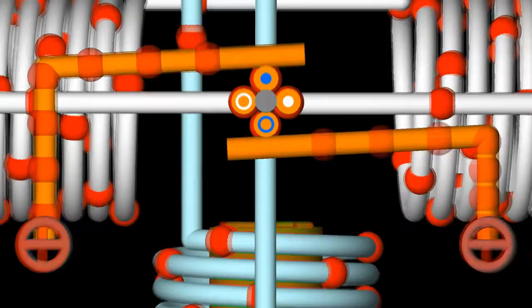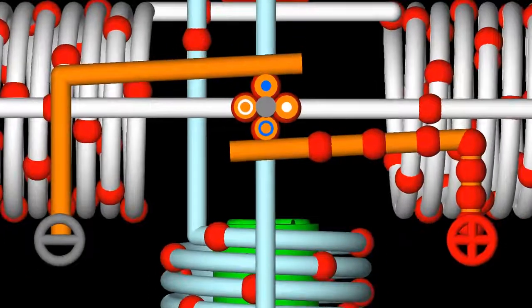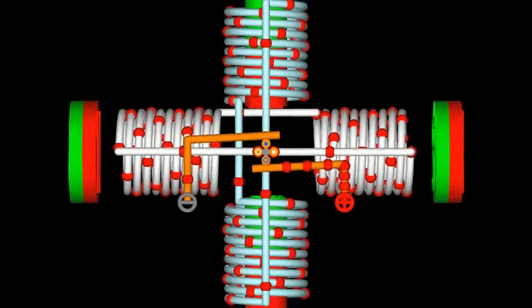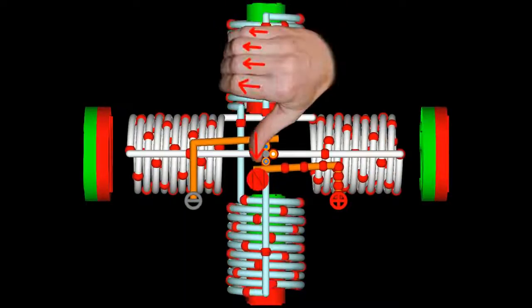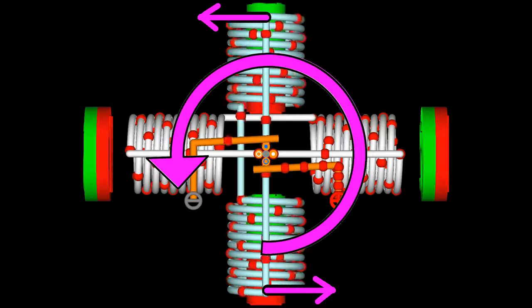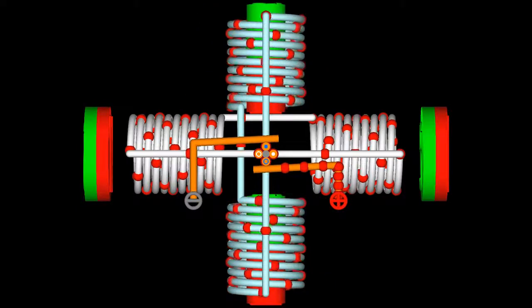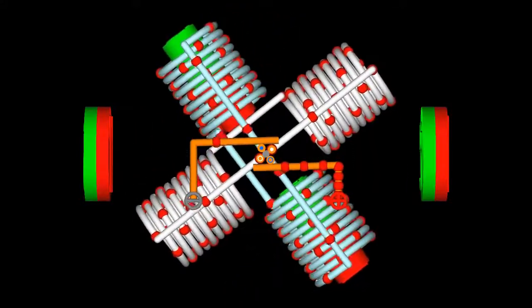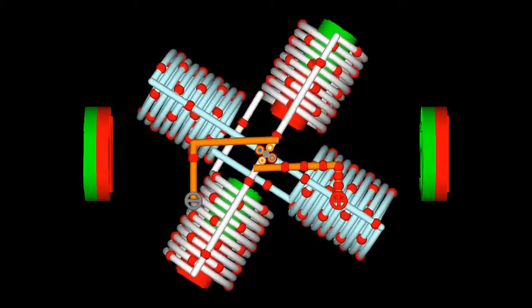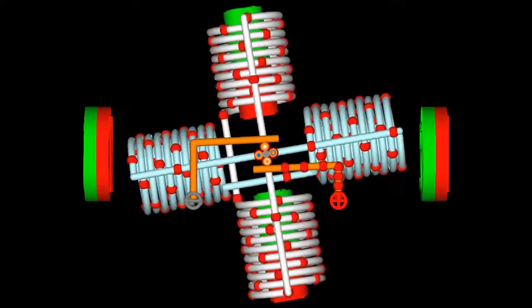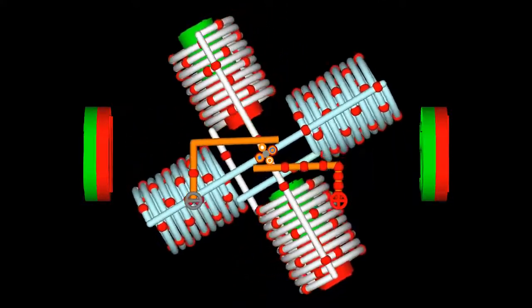Let's swap the polarity of the brushes next, thus the right brush gets connected to the positive terminal. With your right hand you can determine that the magnetic north pole of the light blue electromagnet points downwards by now. The resulting torque points counterclockwise. Same is for the white marked electromagnet whenever it is energized by the commutator. There is a continuous rotation pointing counterclockwise.